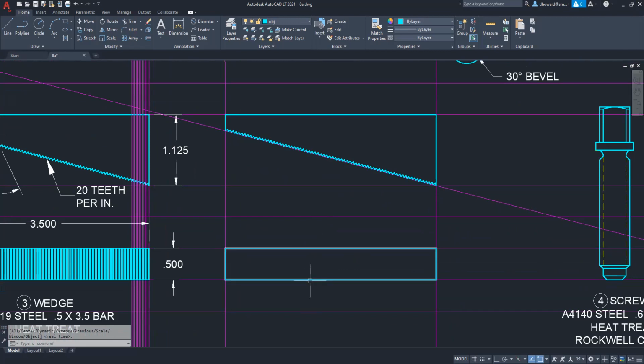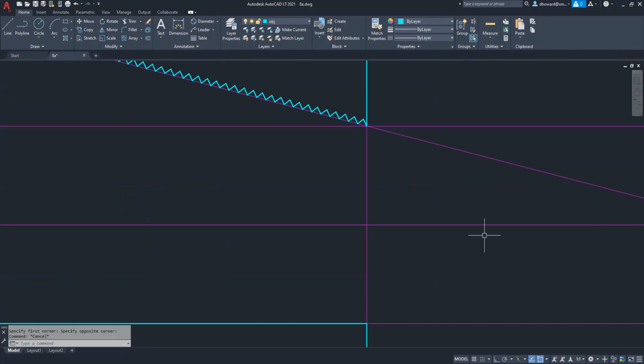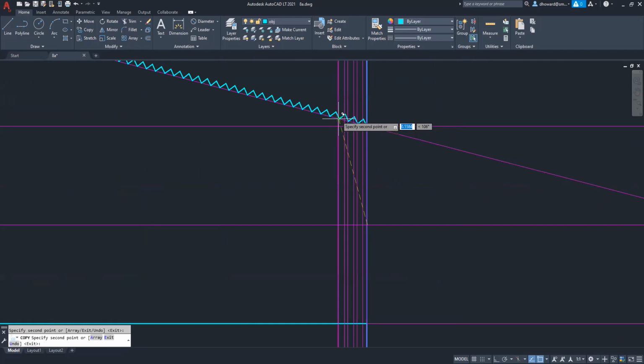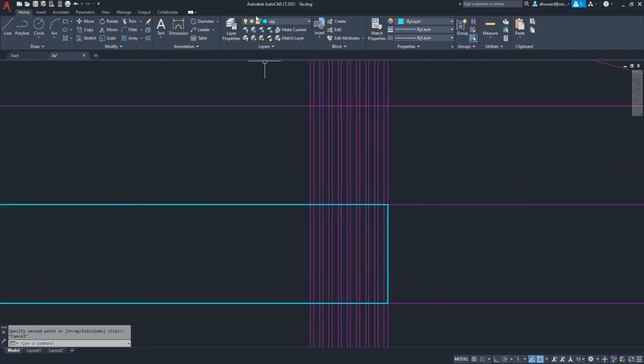And then this front view, looking at the teeth head on, I just made a section of it here, dropping down the construction lines and then copied the rest. So zoom in and see how we do that. Just copied a construction line here to each peak, I should say each crest and root. That's enough. And I'll trace those over.